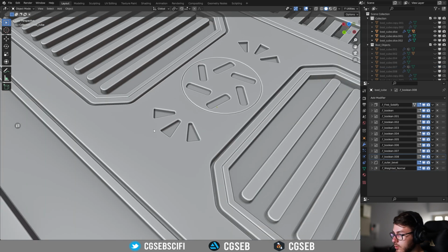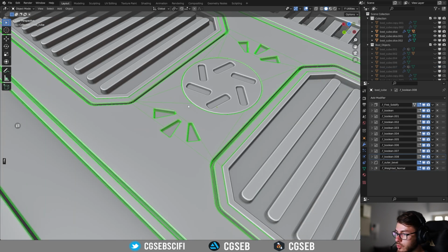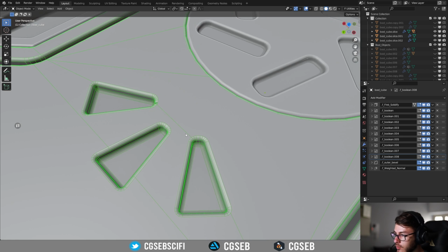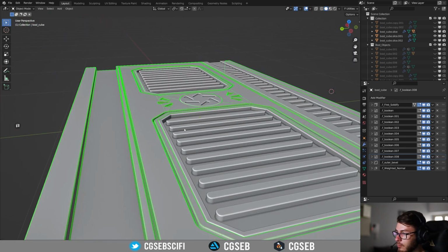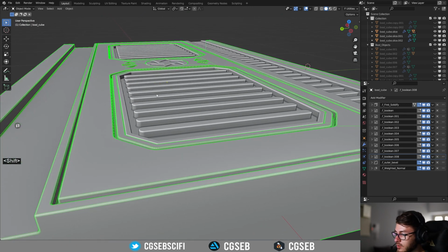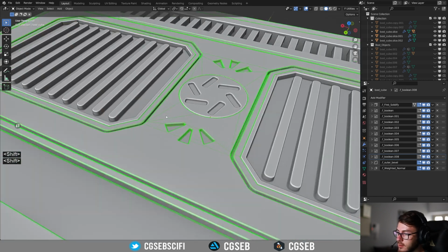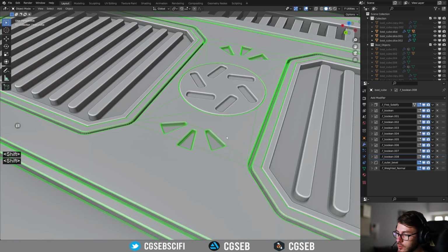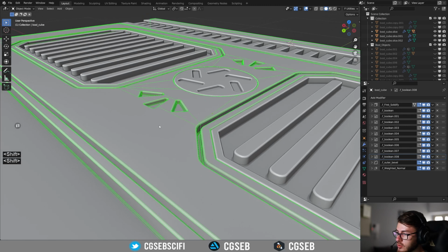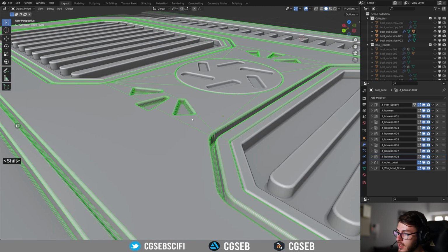So as usual, we show the wireframe and we need to help Blender understand to put a line over there and not in the corners. This is a little bit special because whenever you add support edges, you always need to ask yourself what is actually creating the face that we are working on.